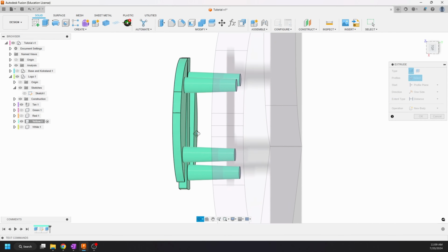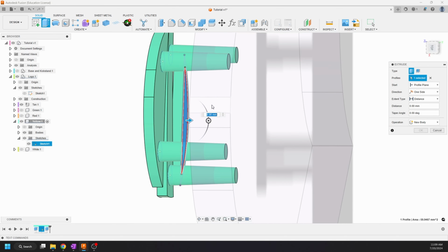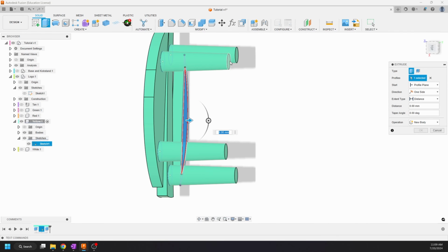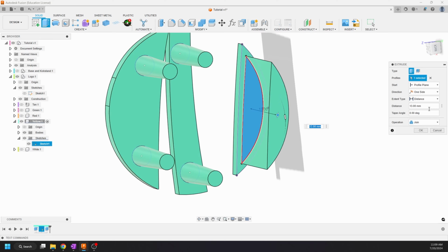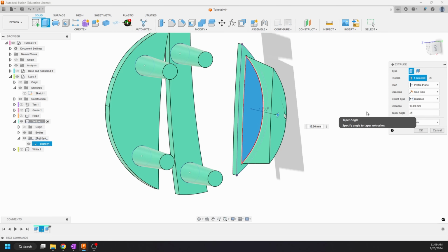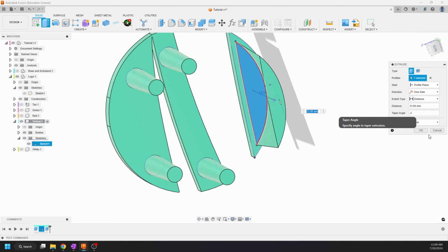Do another E for extrude. Turn the sketch back on. Like that. Select tan and just click the end of this and it will extrude that. We can try the taper angle on here. Let's try -2. Okay, that one does work. So if I can do the taper, then I do the taper. This is a pretty simple shape, so I was able to process it.